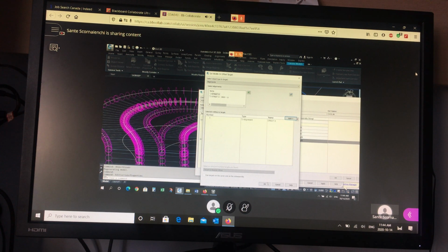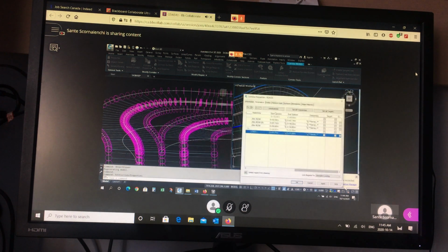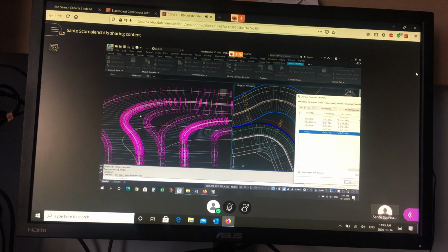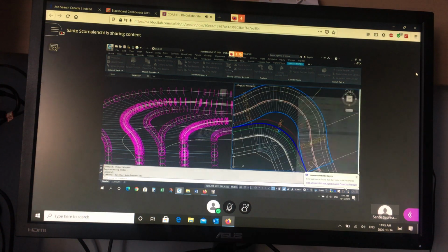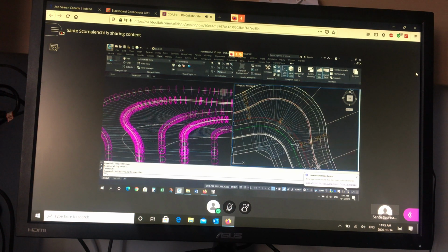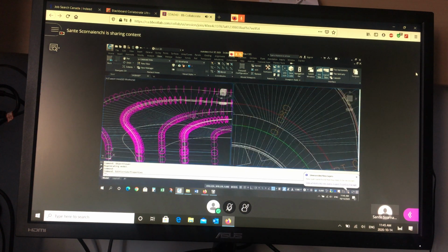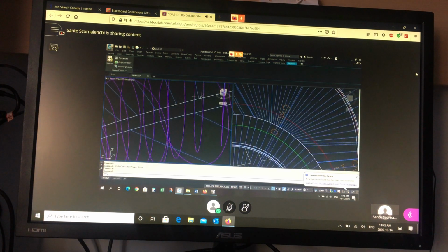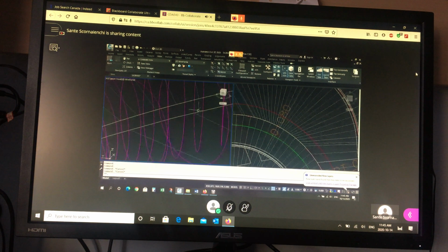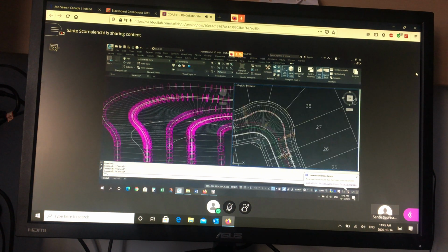Okay? Say okay. And when I say okay, watch what happens in the plan view. Watch what happens in the 3D view. Say okay. And I'm going to rebuild. And now they all stretch. They all get longer to touch the main road center line. Okay. But if you zoom in here, you'll see, it's hard, you can't see it in the plan view, but in this 3D view, you see the elevation. There's a gap here. Vertically, they're not the same. So horizontally, they have the same position. So in the plan view, it looks perfect. But in the vertical, it's wrong. They don't have the same elevation.